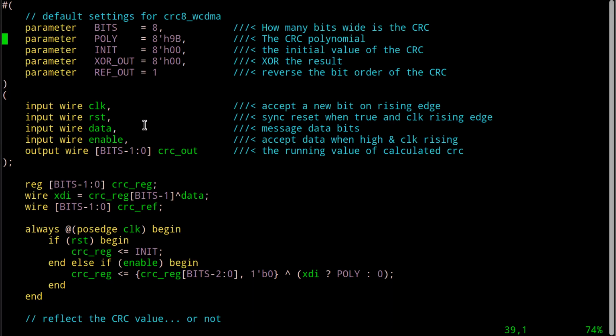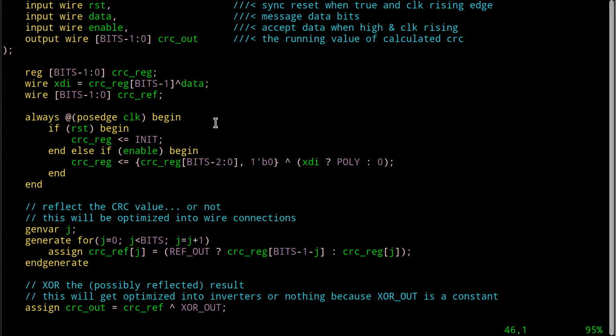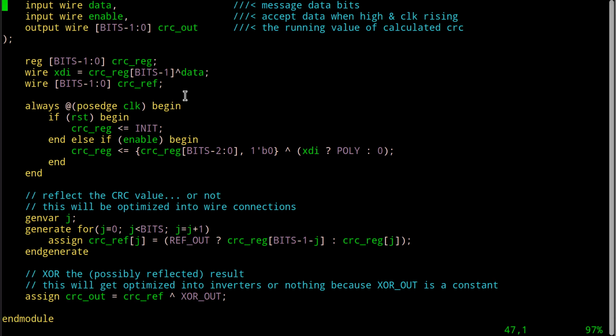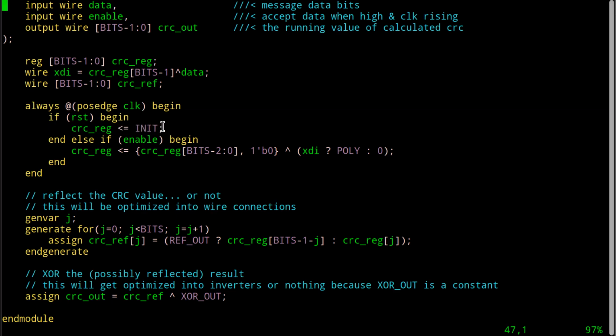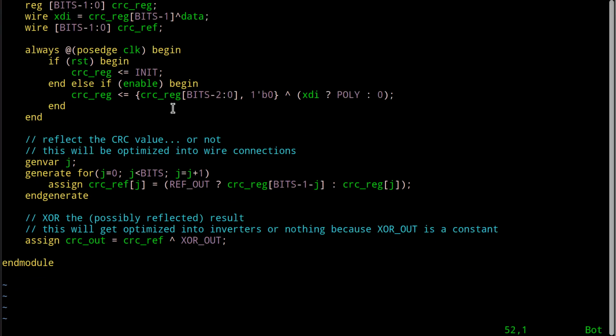Okay, now, when we look at the waveform, you'll see the CRC out is available immediately rather than after a bunch of zeros are clocked into the circuit, which is useful if you cannot wait after the message has arrived, because more data might be arriving right away, and it can cause a problem, which is why you don't normally do it that way. A couple of wires and things for the circuit. As I said, when it's reset, we put the initial value in this, we preload the CRC register as appropriate.